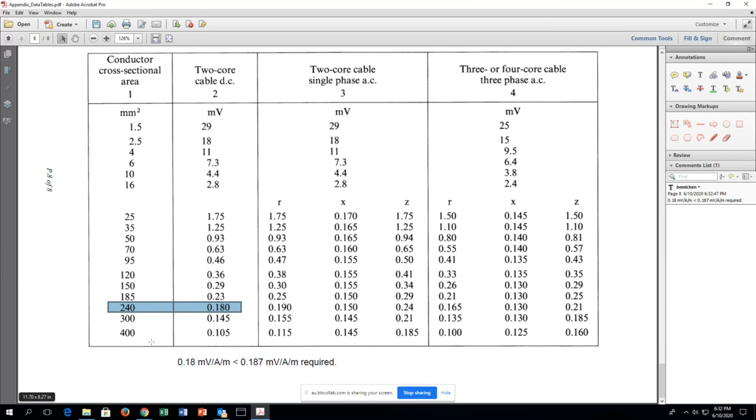Okay, so in practice, we have to make sure that the voltage drop on the cables is smaller than, say, 2.5% or 1.5%, so that the voltage from source to the load is within certain values. Okay, so this is the end of this example. If you still have some questions, you can write to me using the chat box or by email after the tutorial session. I hope that you have no more questions about the DC systems.